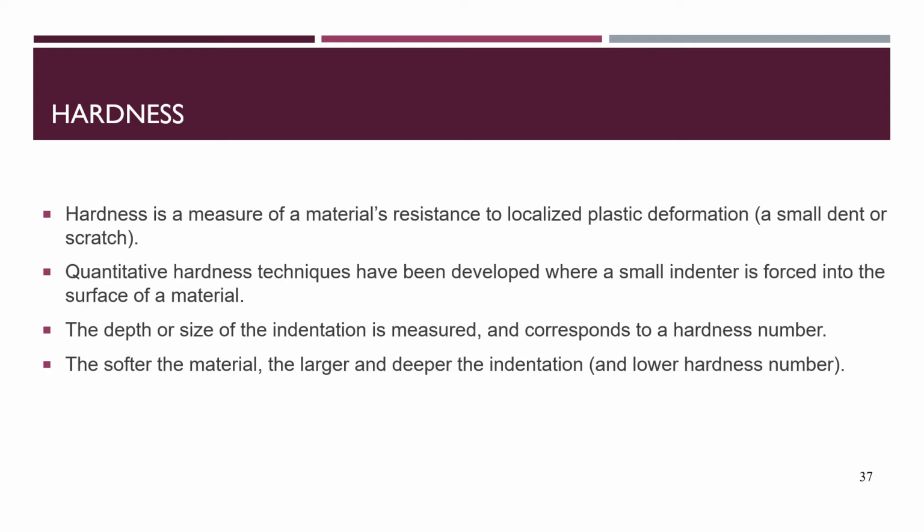The depth or the size of indentation is then measured, and it corresponds to some hardness number. The softer the material, the larger and deeper the indentation. Thus, the lower the hardness number.